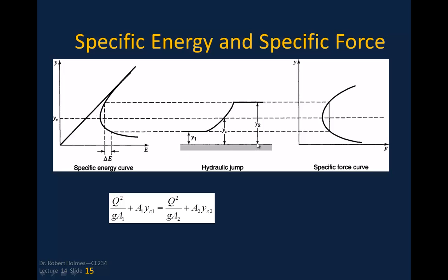This is horizontal, so we have no difference in the Z, the Z1 and Z2. And you can see that we're now in subcritical flow conditions, but we have lost specific energy, and we're back over to here. Now, characterizing that change of specific energy is what makes it problematic in these hydraulic jumps. It makes it problematic to model this with specific energy equations or energy concepts, because it's very difficult to predict this internal energy loss.